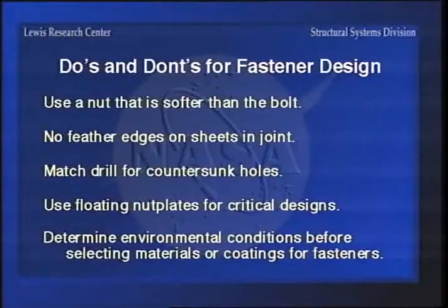That'll keep you out of trouble and that it distributes the loads on the thread, because usually if you torque a fastener to failure with a nut, it will fail in the first two threads in the thread runout area due to stress concentration. So the nut will not fail usually. It's the bolt that fails. And don't use feather edges on sheets in a joint.